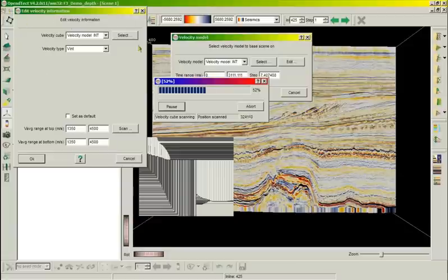And if the data is a velocity model, it needs to be tagged at all locations where velocity models are requested. So that is when gridding velocities in the volume builder, when creating time depth scenes on the fly, or while performing time depth conversions. Eventually also picking velocities.